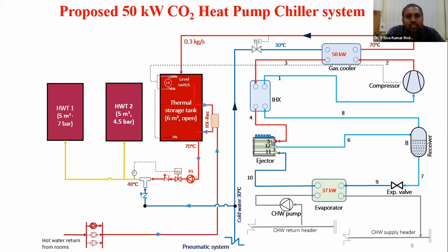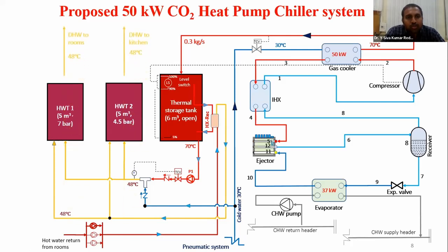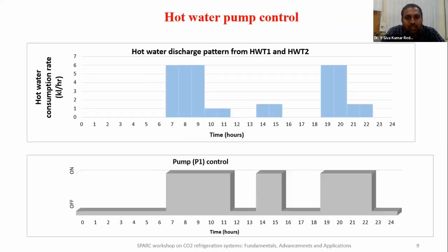And as I explained, this is the heat recovery heat exchanger. So this is how we are controlling this heat pump as well as this pump to serve the hot water demands for the hotel. And this is the hot water pump control. Based on this hot water discharge pattern, this pump also is being controlled.